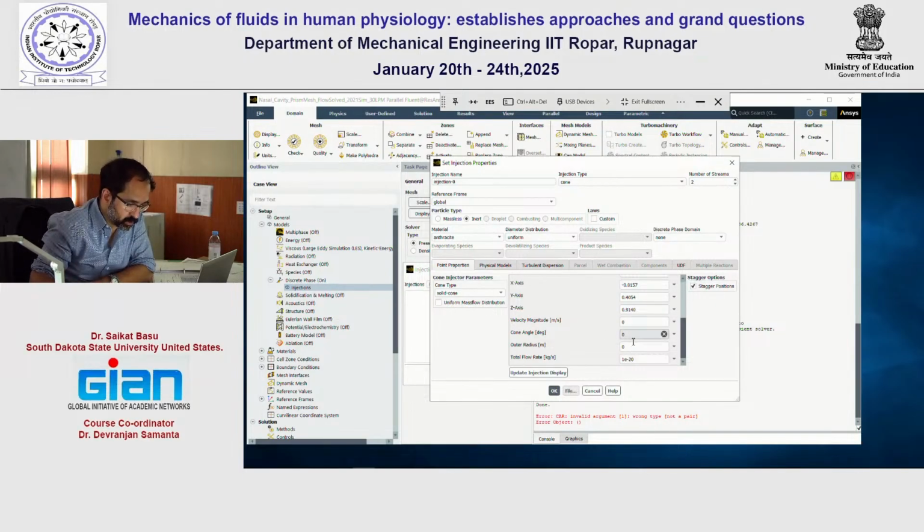Okay. So the cone angle of 30 is what I had assumed, but as you can tell, there is a range, and each spray product would have a mean value, and we can test that. The actual value could be for one of the very popular spray products in the US. The value I can remember right now is 31.16 degrees, that half cone angle. The velocity magnitude is 10, again coming from literature and the laser diffraction studies that we have conducted collaboratively.